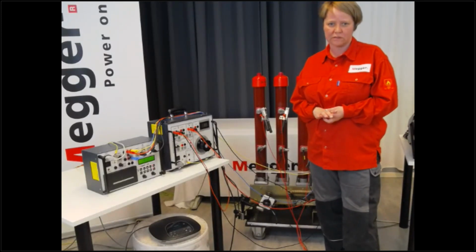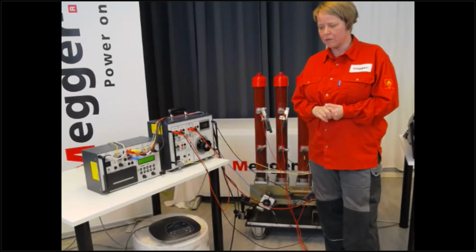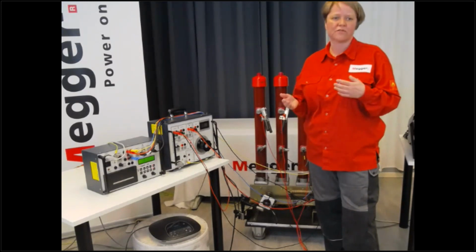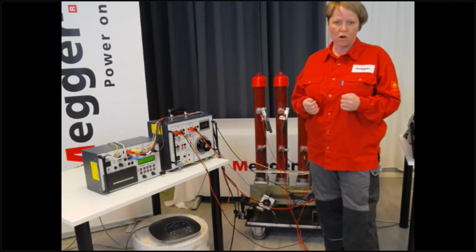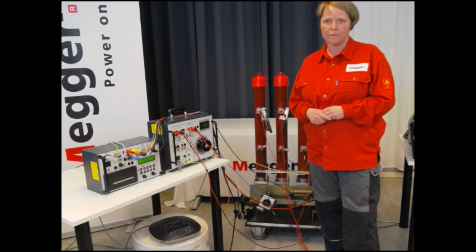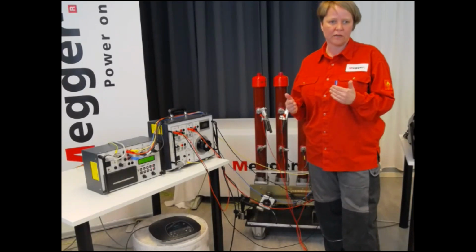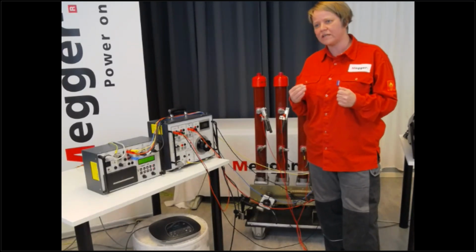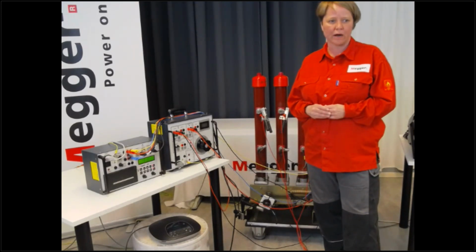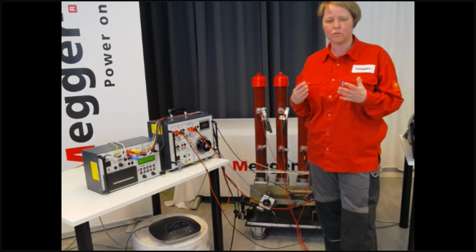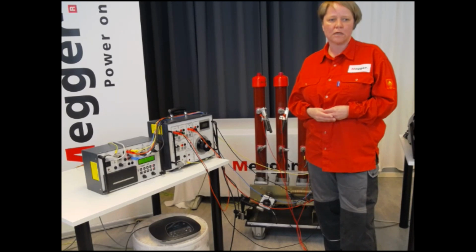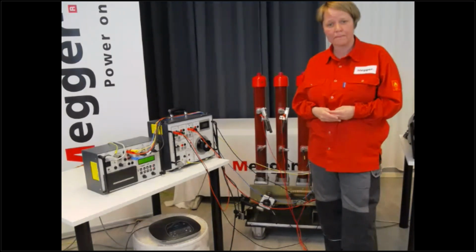We have had a few incidents recently in Europe where people have connected the supply to the breaker because there are other persons in the station, or a mistake between different operators who are not used to working together, so they have misunderstandings. So it's very good to work with both sides grounded, because then you have a protected area where you are working. If somebody does a fault like that, the current would go through the grounding leads instead of down to the instrument.